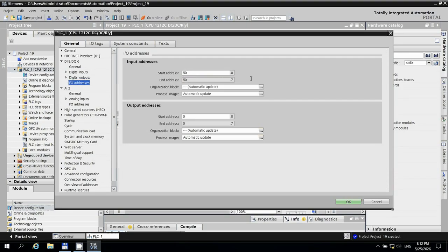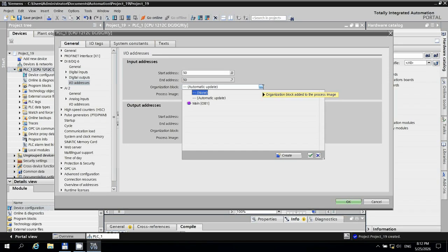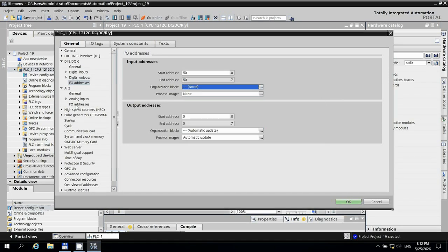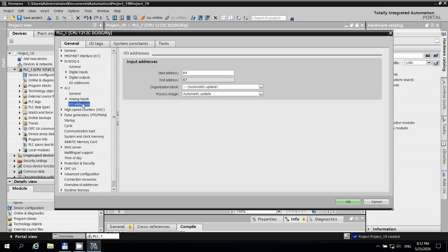These addresses should be moved because working at the same time the portal, Plcsim and the process simulator need to get access to the same memory fields and disturbing each other. That's why they should be moved off any offset and then the inputs are used normally. I change the start addresses digital and analog inputs. There is no need to change the outputs, they are only read.